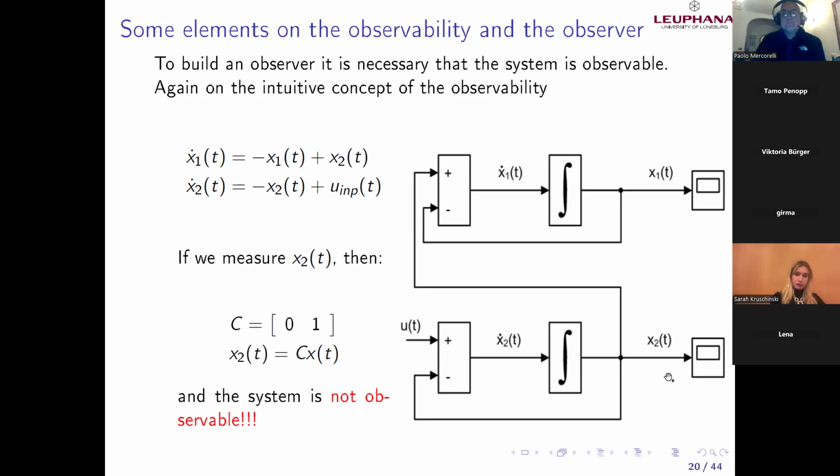What about x2? Once we understood x1, or this way to translate the x1 dynamics in the x1 block, now for x2, no problems. Because between x2 and x2 derivative, as before, I can put an integral. Because the integral of x2 derivative, if I know the initial condition of x2, equals x2.